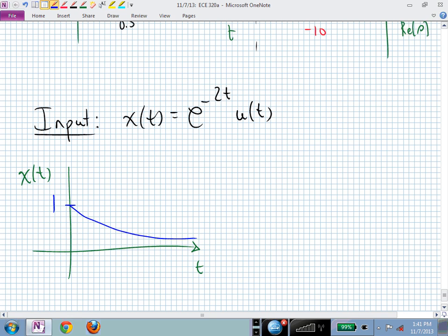It's 1/2, isn't it? It's whatever is below t to get me a minus 2. If I divided t by 1/2, I would get a 2. So my time constant is 1/2. How many of those do I have to wait before I don't really see anything? 5 will get me below 1% of 1, so that's at 0.01. I'm not going to be able to see that. That will be 5 times a half, so 2.5 seconds. This input is much slower than my system response. My system responds quickly enough to be done in half a second.